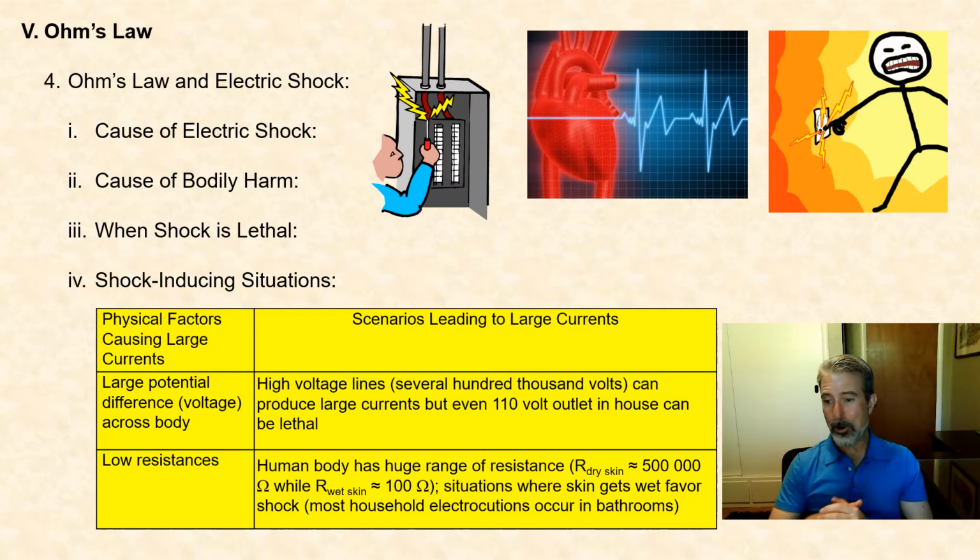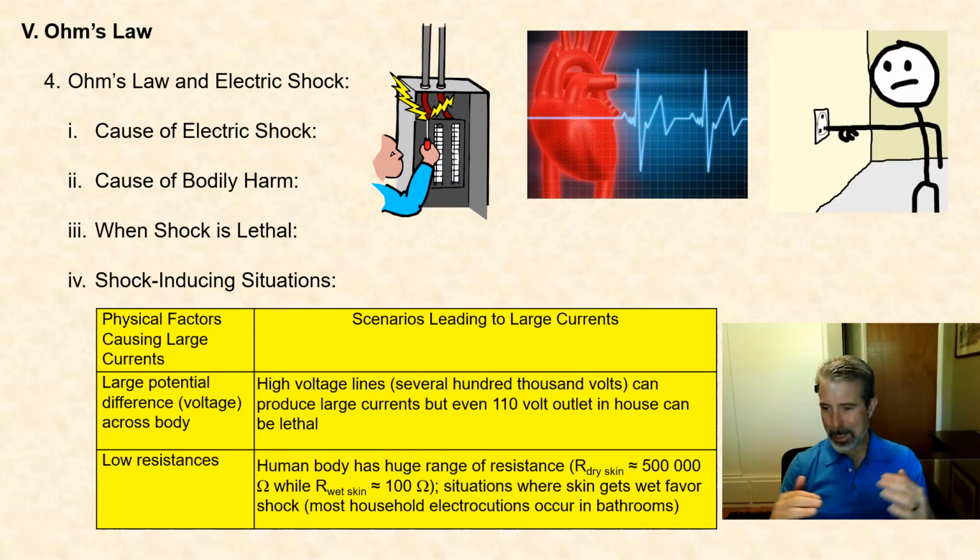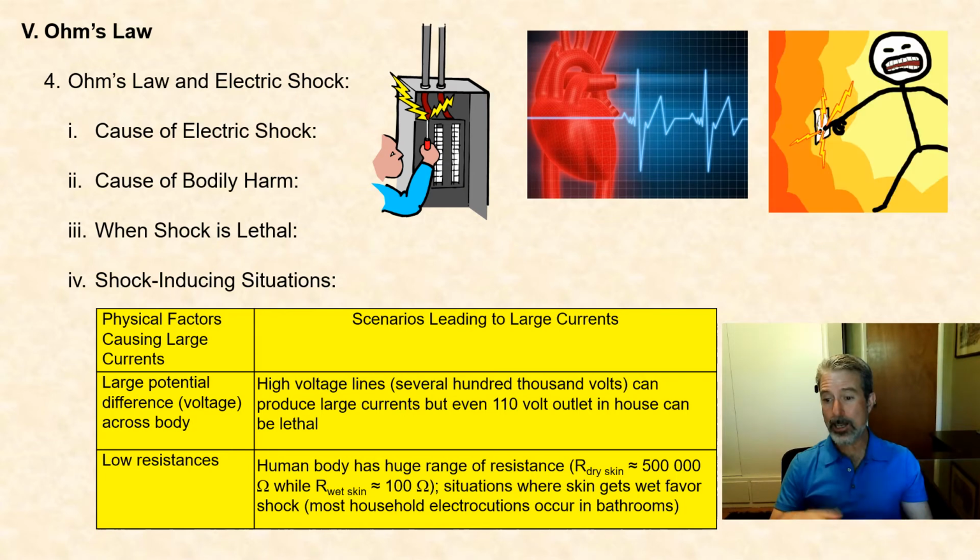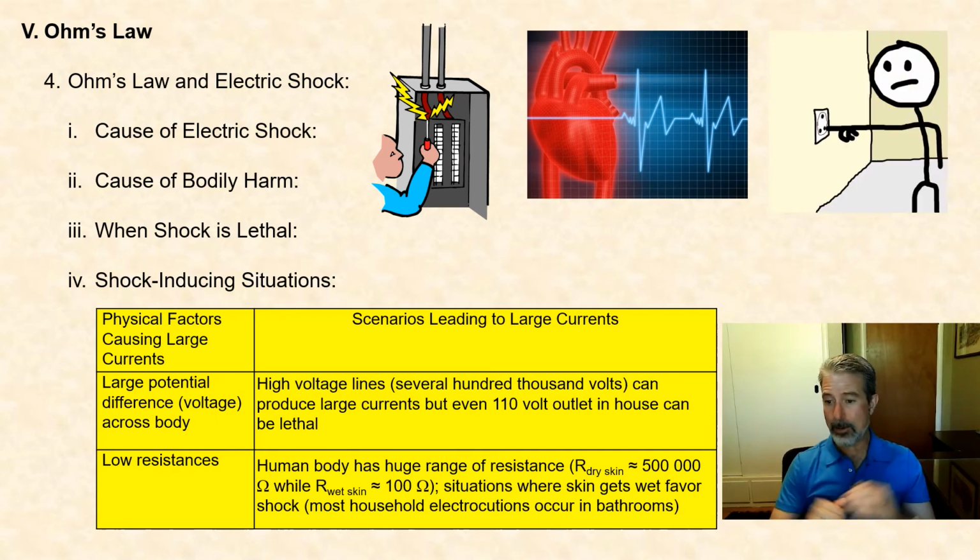So you're in a situation: wet skin, low resistance, connected to a good floor conductor with nothing really between your skin and the floor in the way of insulation. Okay, you are putting yourself in a shock-induced situation where a faulty appliance can easily kill you.